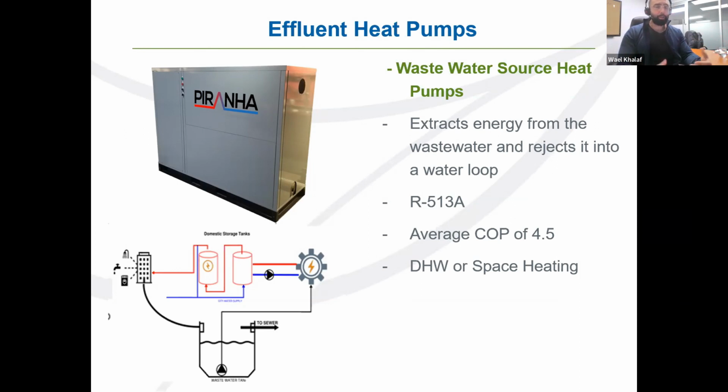And again, we can use this for domestic hot water production, space heating, and/or cooling. So again, very interesting machine, very different from your typical commercial applications. But it is a specialty machine where you have to tie a sanitary sewer system into this machine in order to extract the energy out. Then you take that sewer water and send it back to the municipal infrastructure for it to be pumped towards a pumping station or a water treatment facility.